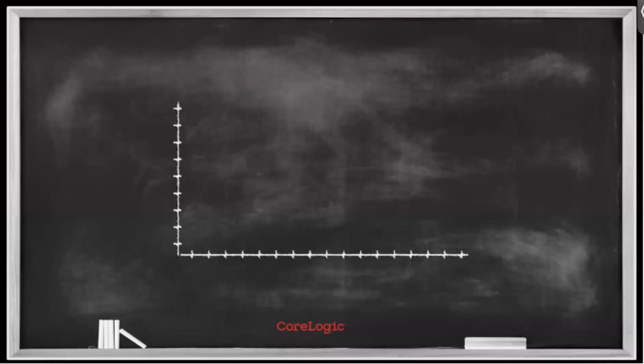And I want to start with, as Stephen Covey would say, start with the end in mind here and talk a little bit about just evaluating your humidity control once it's in, because I think that's an important place to start so that we can back into the finer details of humidity control. So to start this off, first of all, when we're evaluating humidity control, there are two ways that we can look at humidity, right? We can look at relative humidity or we can look at a humidity ratio, sometimes referred to as an absolute humidity, specific humidity, all depending on how we're measuring it, what scale we're measuring it with.